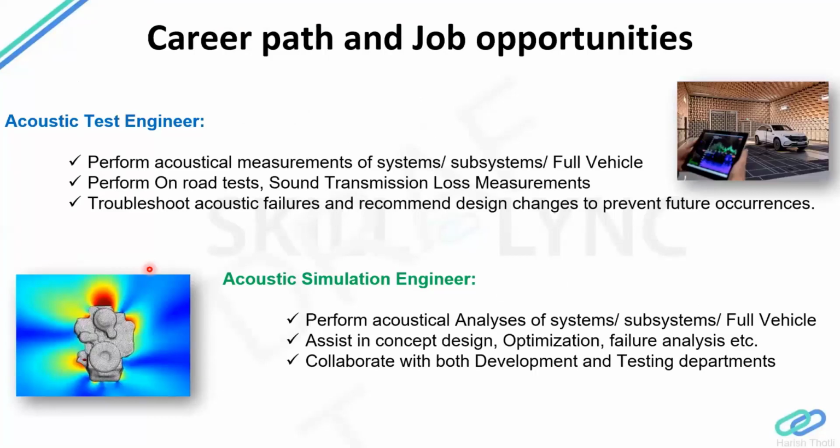And coming to the main tasks performed by acoustic engineers. As an acoustic test engineer, one performs acoustical measurements of systems, subsystems, and full vehicles, and should also perform on-road tests where you sit inside your automobile and drive on the highway in the night for a few hours and check for the noise coming from the powertrain or wind or road noise, and again the sound transmission loss measurements like an impedance tube, for example, and troubleshoot acoustic failures. This is also one of the key tasks of an acoustic engineer.